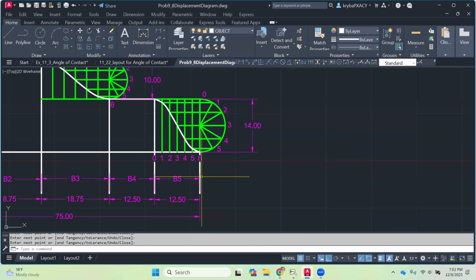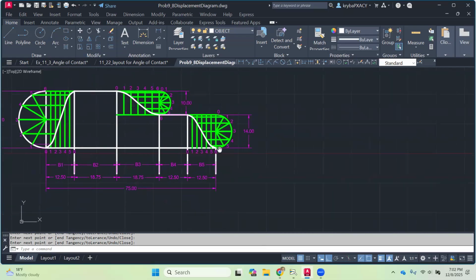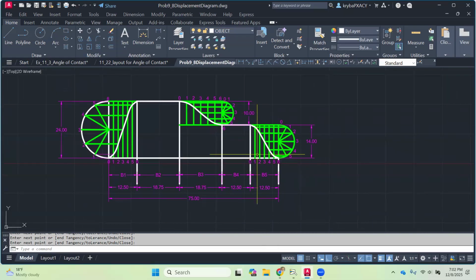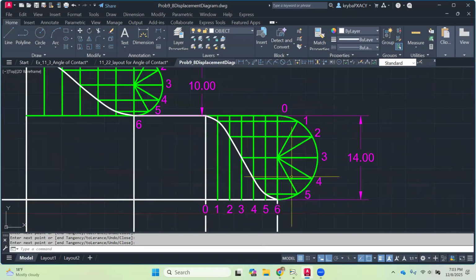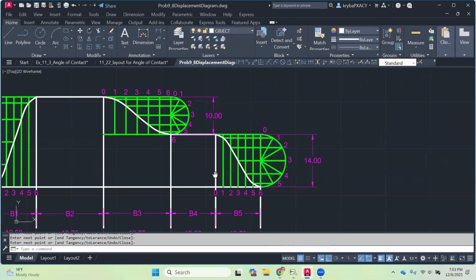Okay. Any questions on creating the displacement diagram? And then this would be minimally what you need. I do want to see the construction of, in this case, the harmonic motion. Jacob. These angles? So remember, it's 6 divisions and it's 6 even divisions on 180 degrees. So 180 divided by 6 is 30 degrees in between. Yep. Good question. Any others?